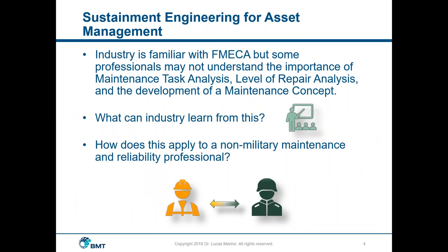A lot of our listeners may be familiar with FMECA, which is the failure mode, effects, and criticality analysis. The simpler form of this would be FMEA. But many people in industry don't understand that there's more that follows after that in the world of sustainment engineering. We move right into things like maintenance allocation charts, maintenance task analysis, and level of repair analysis.